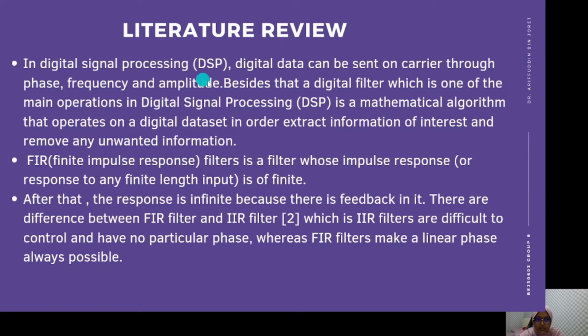First of all, in digital signal processing (DSP), digital data can be sent on a carrier through phase, frequency, and amplitude. Besides that, the digital filter, which is one of the main operations in digital signal processing, is a mathematical algorithm that operates on a digital dataset in order to extract information of interest and remove any unwanted information. An FIR filter is a filter whose impulse response is finite for any finite length input. After that, the IIR response is infinite because there is feedback.